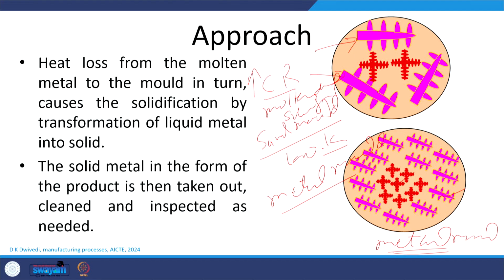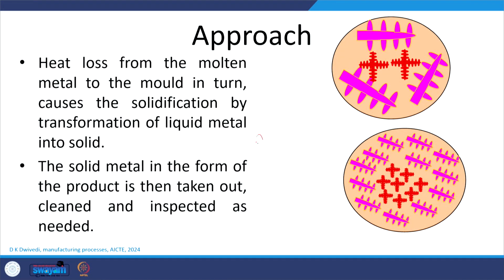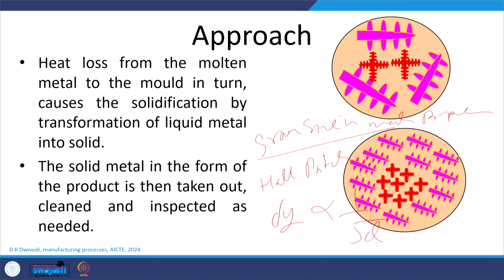So, the wider or larger interdendritic spacing and coarse grains are produced, and we know that the grain size plays a very important role in the mechanical properties. Grain size affects the mechanical properties significantly, and we simply have the Hall-Petch relationship for this. According to that, yield strength is found inversely proportional to the square root of the grain size, say average diameter of the grain. So, if we see this, then the metallic mold will be resulting in the finer grains, meaning smaller d value, and that in turn will result in the greater yield strength.